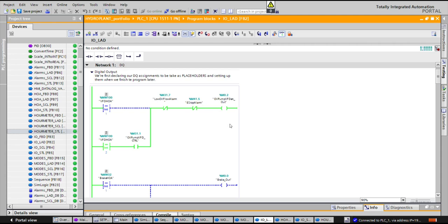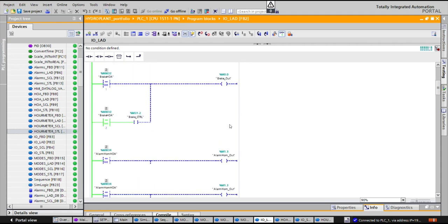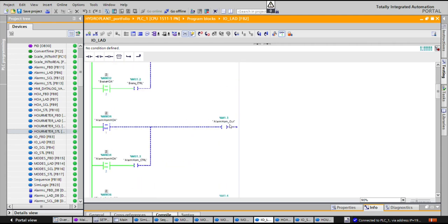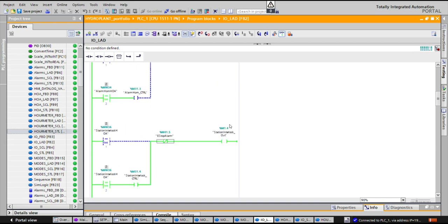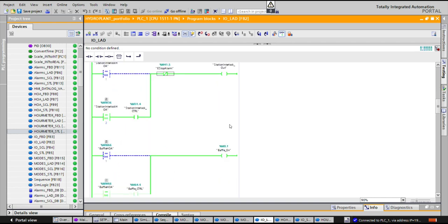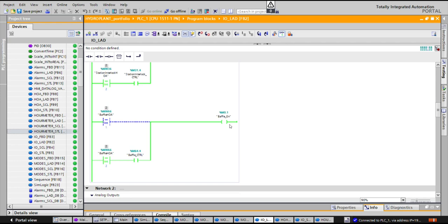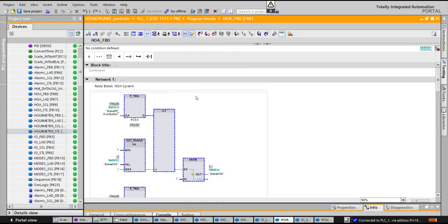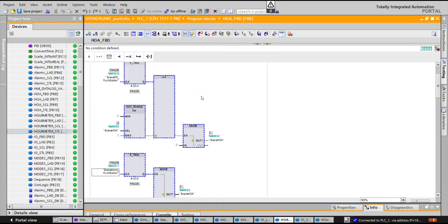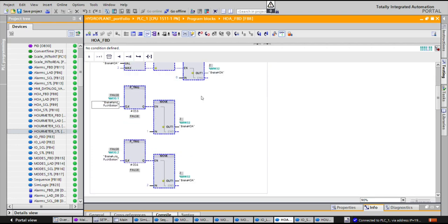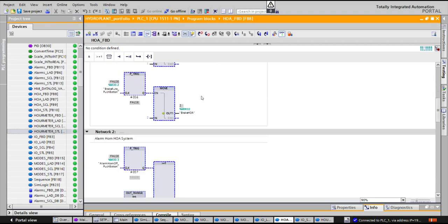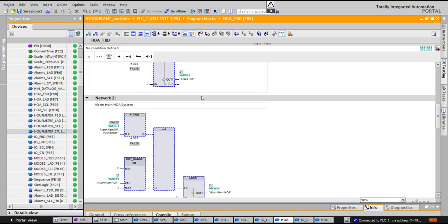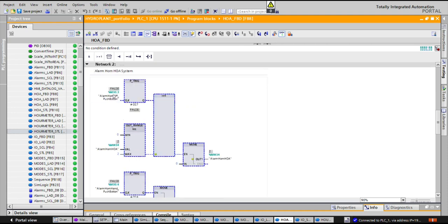Depending on the language that we have selected, a determined function block language will be energized. In this case, this function block controls the I/O devices' logic, and if all devices are in auto mode, a control bit will be activating and deactivating our devices. Changing to function block language, we can see that by pushing the HOA buttons, the state of the devices is changed.